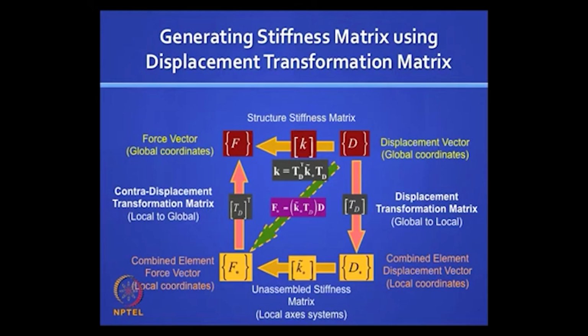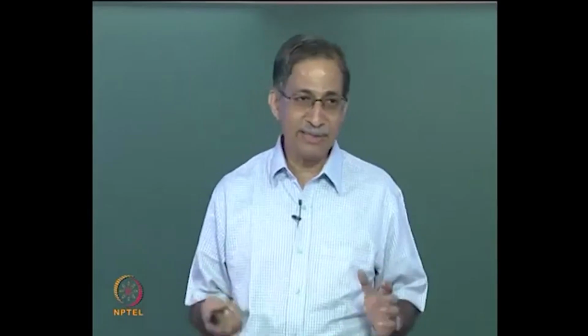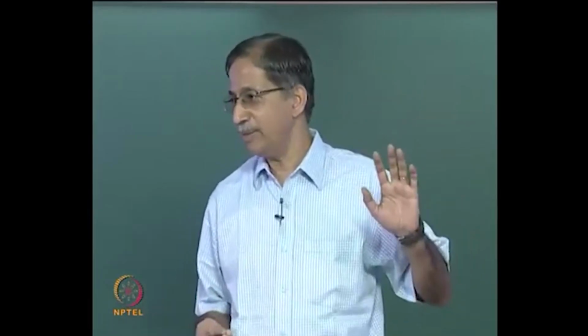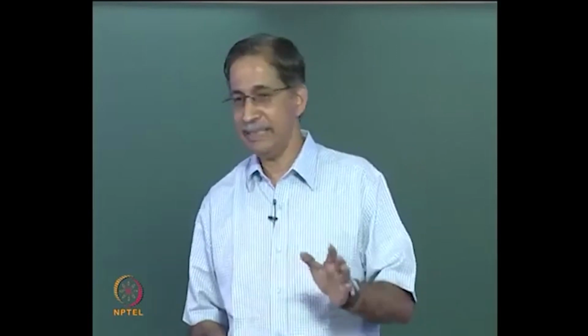So you will find repeatedly this kind of pattern emerging. You have to pre-multiply the stiffness matrix, whether it is the regular stiffness matrix or the conventional stiffness matrix, by the transpose of some transformation matrix, in this case TD, and also post-multiply with TD.